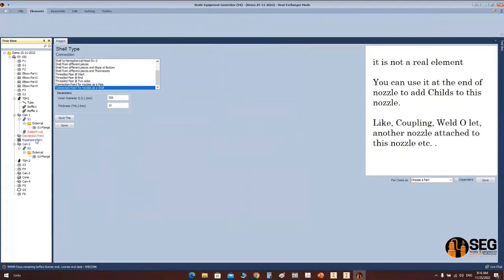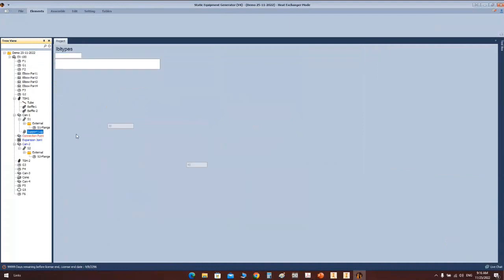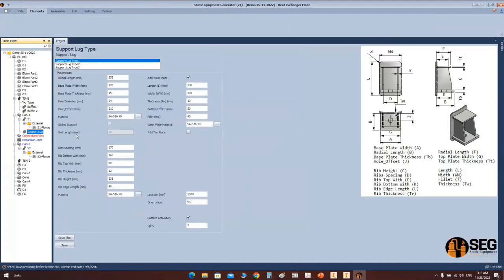As discussed, we have three different colors on the tree. The first one, which is the black one, is for the generated items on Autodesk Inventor, no need to assemble or update because they are already created and updated. The red one means this item is not created yet, or created but needs an update for the parameters.